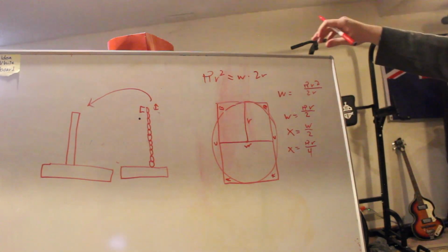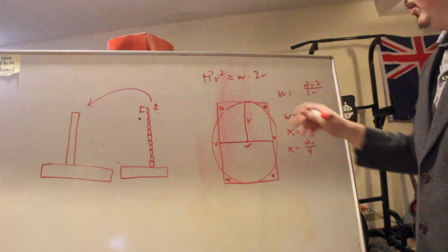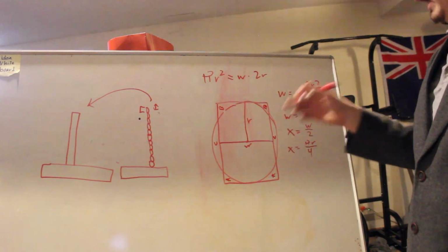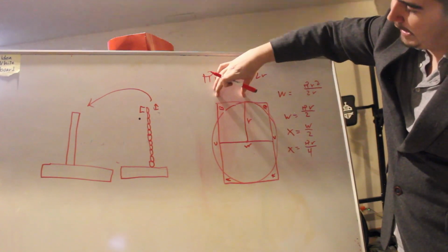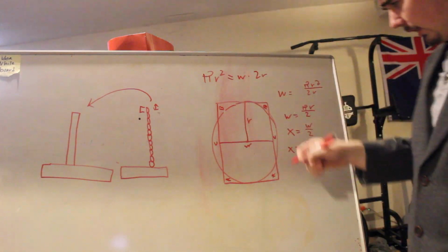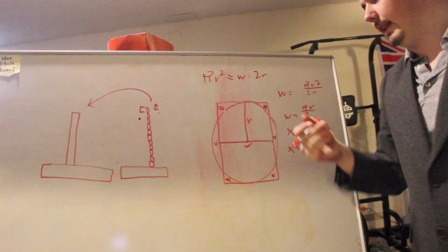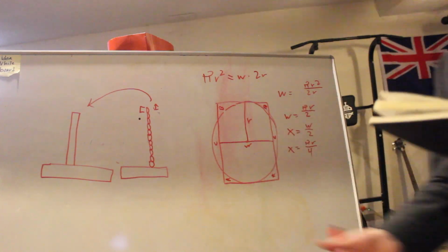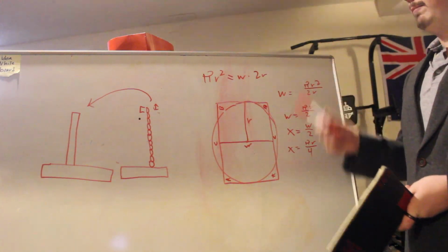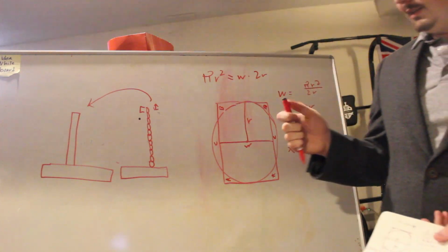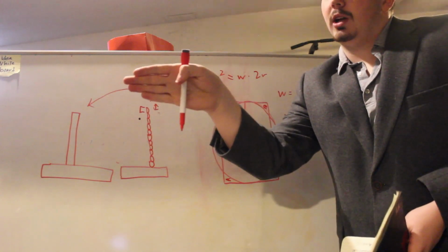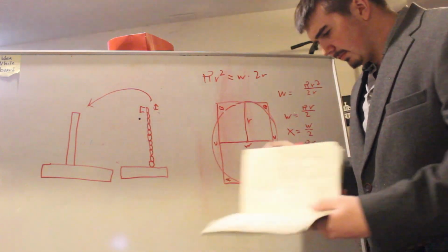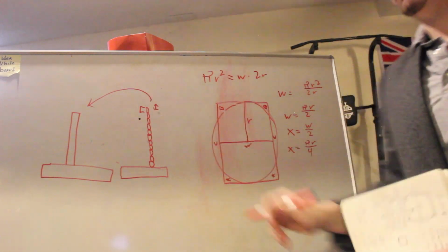So for any circle we're going to do this for, if we know the radius, we can multiply it by pi, divide it by 4, and that is how far away you'll need to hold a smoothing tool in order to fill in the net valleys and peaks of a circle. So we've got our equation. How does this apply? Imagine we had some kind of automated tooling device that moves along with the nozzle. Based on where the G code is following, it can orient itself and smooth off a wall.